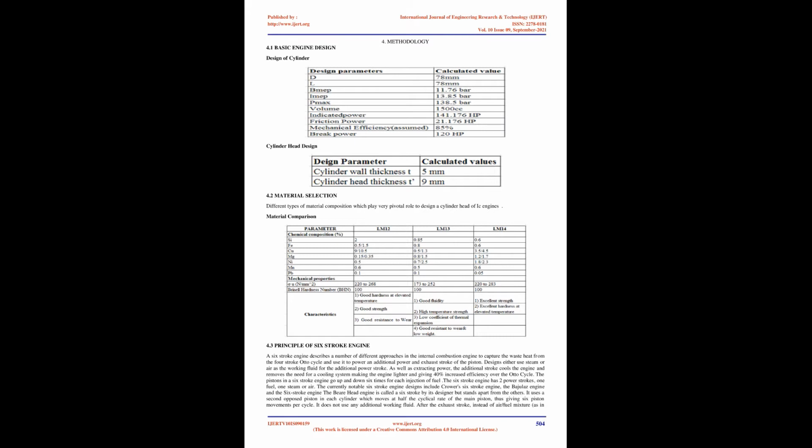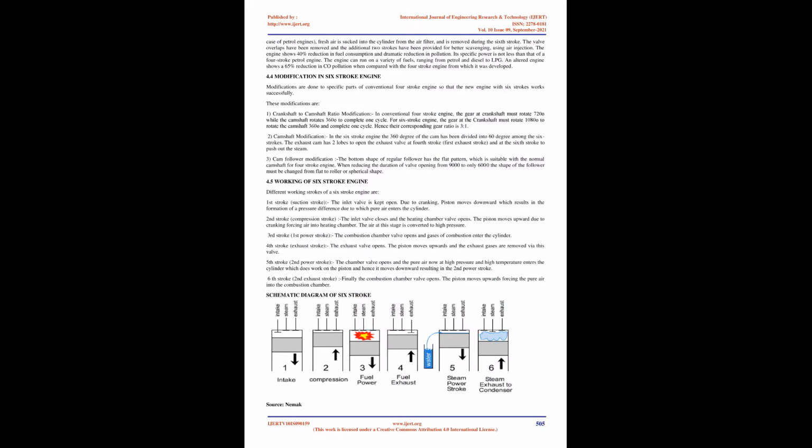Mr. Amal S. Bhagat and Professor Rahul Sakarkar: the cylinder head is one of the parts of an I.C. engine which is responsible for maintaining temperature. One end of it is closed. It contains the inlet and exhaust valves through which the air-fuel mixture enters the cylinder and exhaust gases escape to the atmosphere from the cylinder. In the combustion chamber there are peaks of combustion pressure and temperature on the order of 15 MPa and 2500 K. The heat fluxes and temperature non-uniformities lead to thermal stress, which further escalates mechanical loading from combustion pressure.